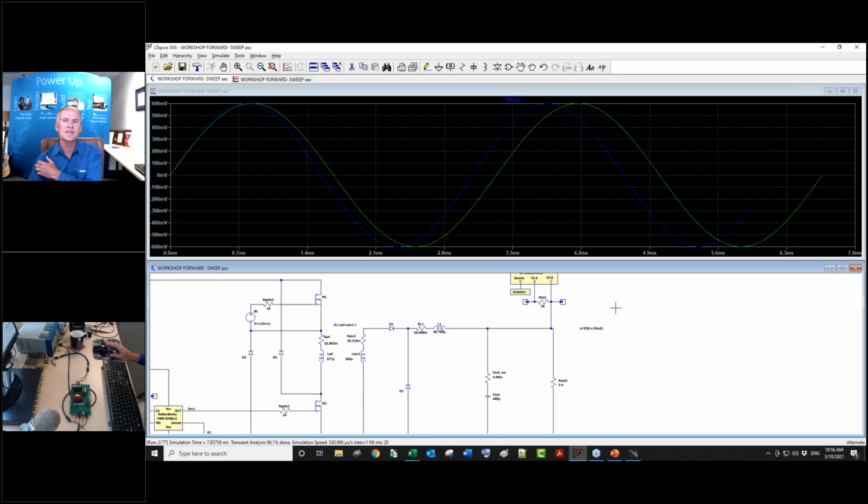This is the injected signal that's going into this circuit. We're measuring a 2-switch forward converter here, and it's measuring the injected signal across the resistor. Right now we're just doing a fixed injection. It's a 1/2 volt injection into the circuit. You can see it sweeping. It started at 300 hertz, a little bit higher, and then it's sweeping to a 100 kilohertz circuit.